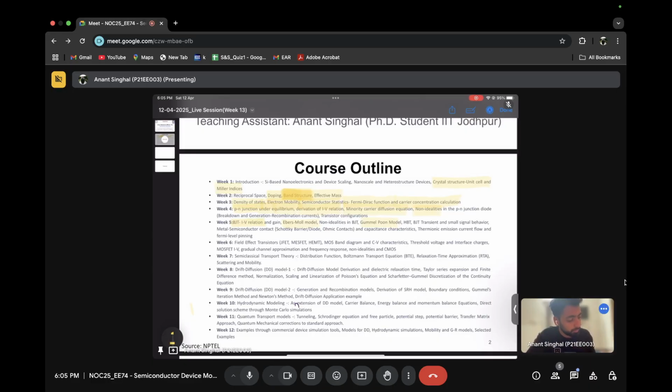But I can say it is not very important, but the important part comes about the semiconductor contacts. So we covered the Schottky and the ohmic contacts, that whenever the metal work function is greater than that of a semiconductor, and there can be a few conditions, either it is a p-type semiconductor or n-type, so we can see what kind of contact it is.